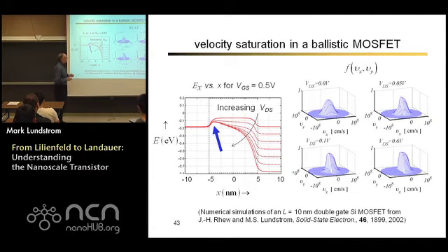Okay. But it's kind of interesting. Maxwellian velocity distributions are produced when you have a lot of scattering so that everything comes to equilibrium. Then you get a Maxwellian velocity distribution. There is no scattering here. How can we get a Maxwellian velocity distribution when we apply 0 volts between the drain and the source? The answer is very interesting.